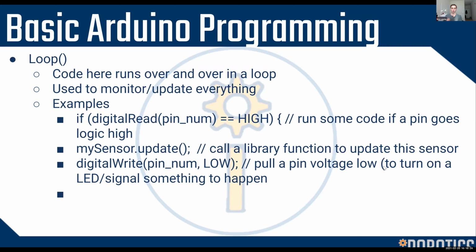So you can control these outputs based on your inputs, and you can keep doing this in loops over and over. So whenever the color sensor goes high, you immediately make sure your motor goes low or high or whatever you want to do. And with whatever steps you want, you can make it wait like 30 milliseconds after it goes high. You can make your motor turn on or off, and basically anything you need to do for the mechanics of your robot and how you want your code to work.